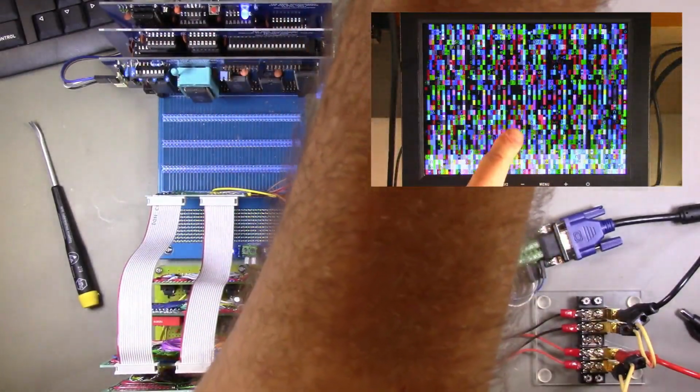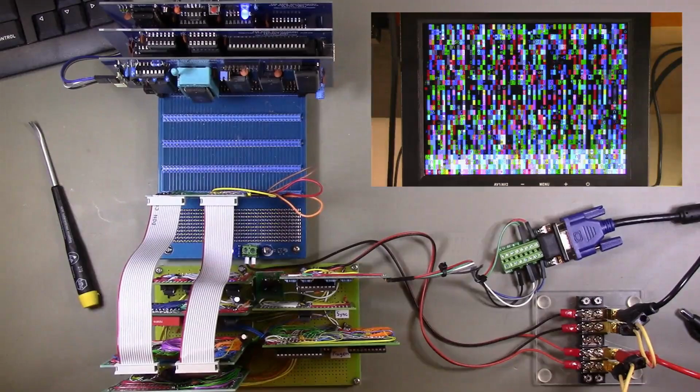And there we go. That is absolutely rock solid, stable 640 by 480 VGA, showing perfectly reasonable font shapes and attribute colors. I was super excited when I reached the point where I had a stable display. I was certainly a little worried that I wasn't going to get to the point where I was able to eliminate the glitches, and it was very gratifying that it turned out to be as easy as using 74ALS logic rather than 74ACT logic.